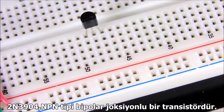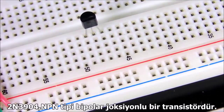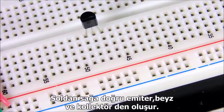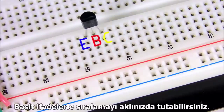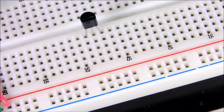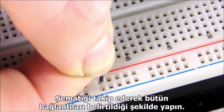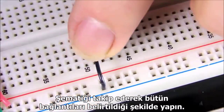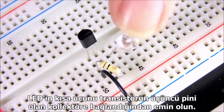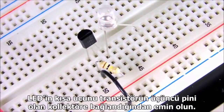The 2N3904, that's a bipolar junction transistor, NPN type. Of course, its leads correspond to the terminals we talked about in the schematic. From left to right, they are the emitter, base, and collector. You could always remember the order with a simple phrase like, "Eat big cookie," or something similar. Anyway, follow along with the schematic and make all the connections as it specifies. Be sure to connect the LED's shorter lead to the collector of the transistor, the 3rd pin.